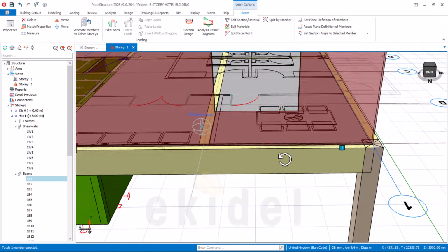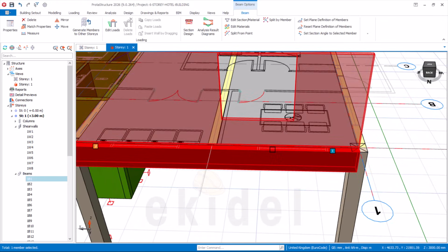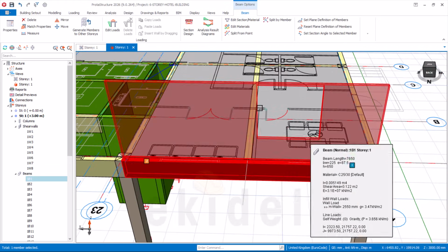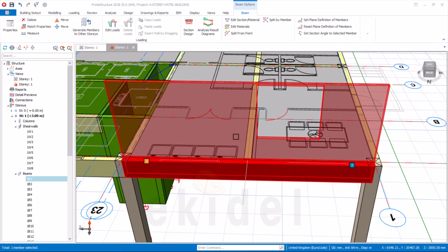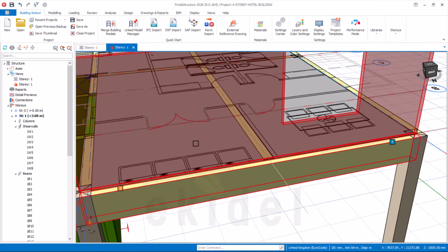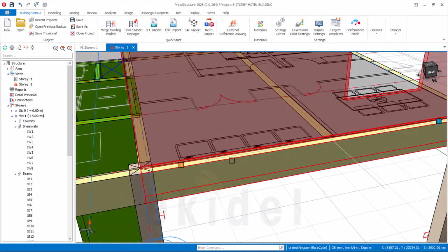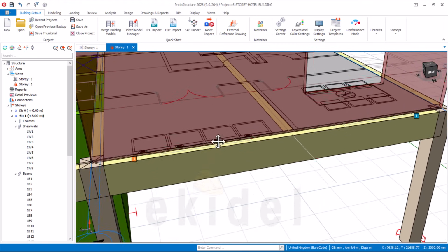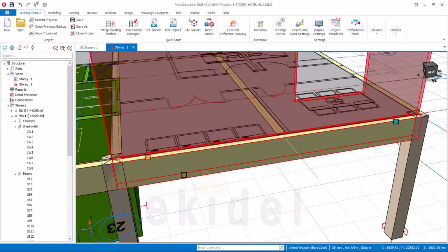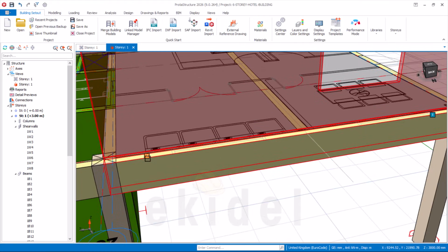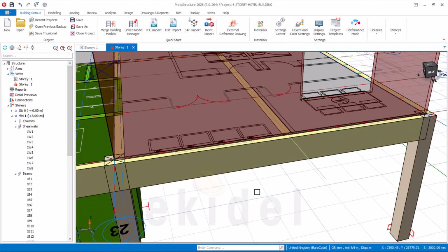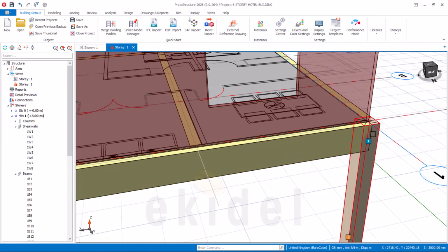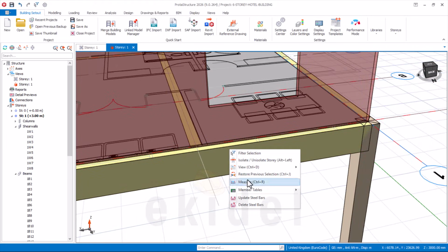This is not where I want the opening to be. The opening was to be here. So let us work on this again. Now that we have this wall already inserted, we can still have our opening, because the opening is meant to be here and then one here after. I said that it starts from J, but sorry, it starts from I. We measured from J, so let's measure from this other end, because you always start from I, not from J. So measure the distance from this point to this place.